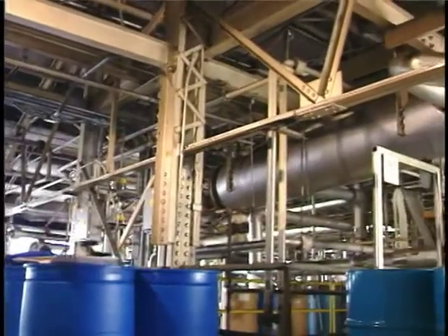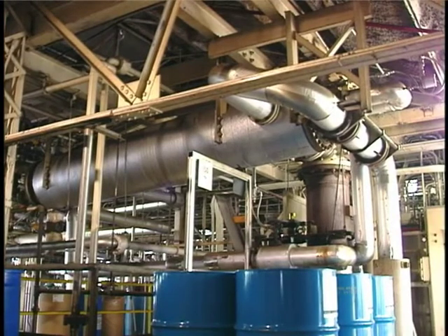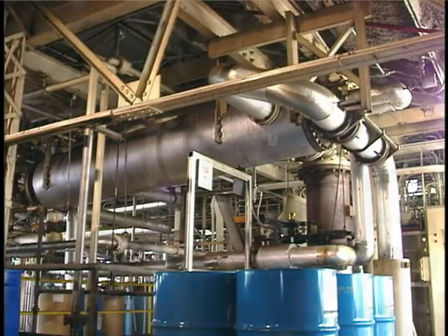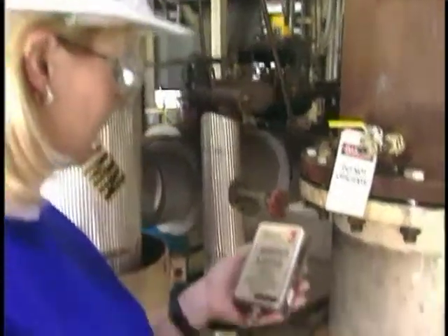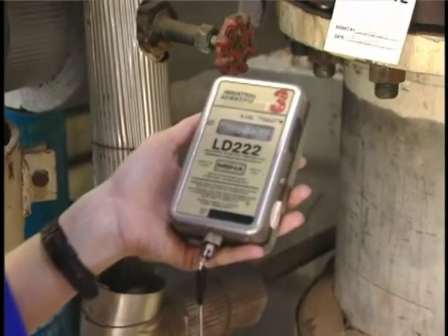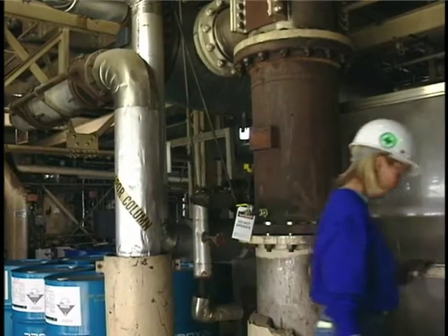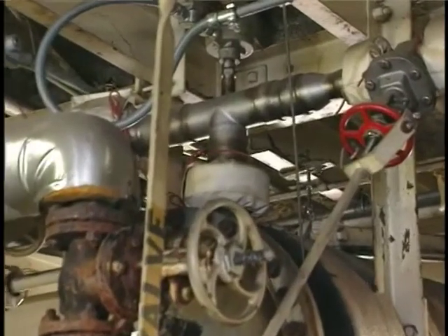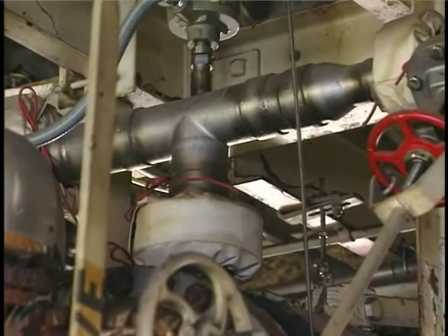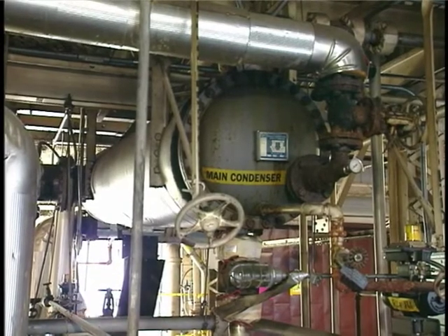Calibration should be performed on a daily basis using a calibration gas cylinder that is less than 6 months old and has a pressure of at least 150 psig. Portable analyzers should not be used to evaluate condenser performance. Condensation systems are often used on sources that generate high organic vapor concentrations. It is possible that during malfunctions of the system, the outlet gas stream concentration could be in the explosive range. Static electricity on the instrument probe could be a source of ignition.